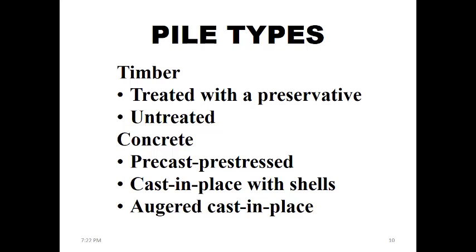So we want to prevent any adverse impact from the environment on the piles, and that's why we use these preservatives. While we have this preservative-treated option, we also have to think about the untreated option. The untreated option will have all the negative aspects that we mentioned as positive for the treated type of piles, but at the same time it reduces the cost of a pile for certain applications where the treatment is not necessary, and we'll talk about it in a minute.